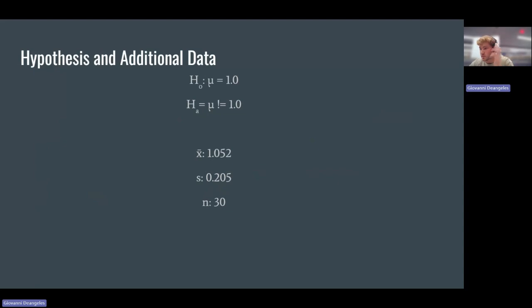So the standard deviation for our machine was 0.205 pounds. This is simply telling us the variation of the seal strength between each tray, which we had 30 samples, so that's between each sample. So it was 0.205 pounds. And this is the normal behavior for the machine. If the machine has a lot of natural variation, a small difference like 0.052 is not surprising. So you won't have to mess with the machine or change anything to it.